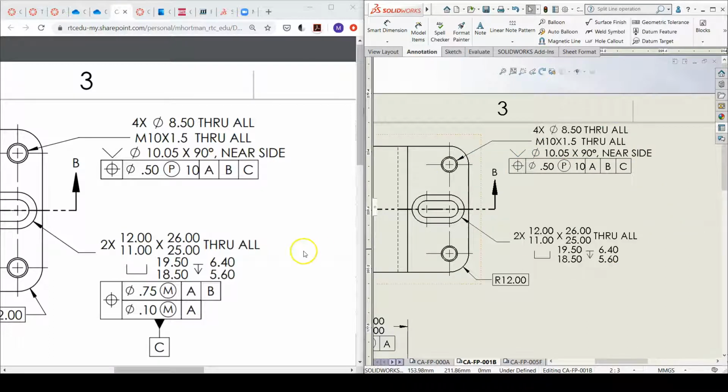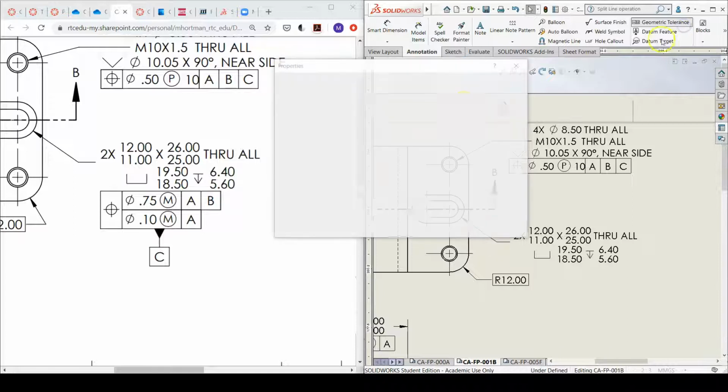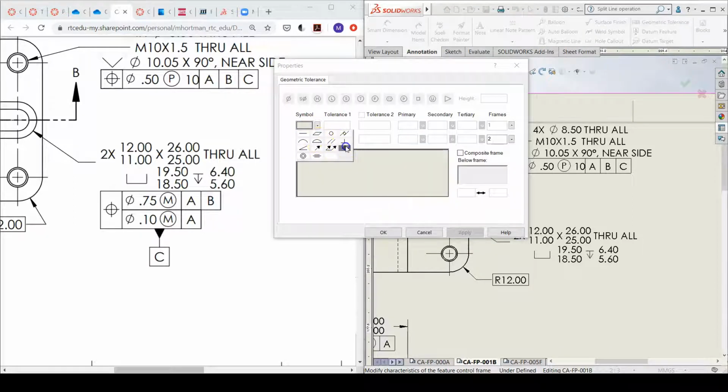Alright, and then the slots is our Datum Feature C, and it's a composite tolerance. What this composite tolerance means is that you can locate the pattern of slots within 0.75 millimeters, but the slots need to be positioned within each other within 0.1 millimeters at MMC. So go to geometric tolerance, go to position, put in my diameter symbol and MMC symbol, put in 0.75 first, then A and B. And then to get the second line, you go to the second row here, position tolerance, 0.10, diameter and MMC symbol, just by clicking on them up here.